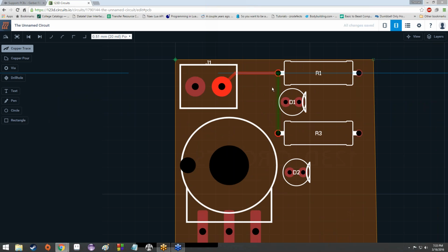to our first resistor. And you notice that as I move the mouse around, I got sort of this wibbly elbow put in here. This is meant to represent the path of the copper tracing. And if I hit right click, I can change the bend of the elbow. It can be a 90-degree angle instead of a 45-degree angle. It can be up, it can be down, whatever I prefer. I'm going to have it be like it was originally, so like this.